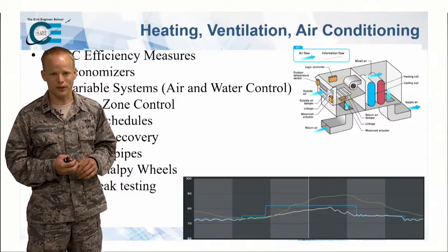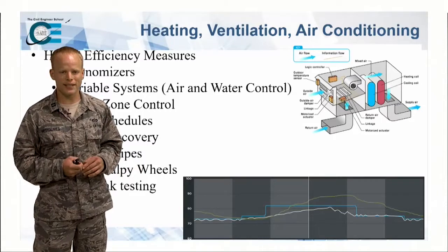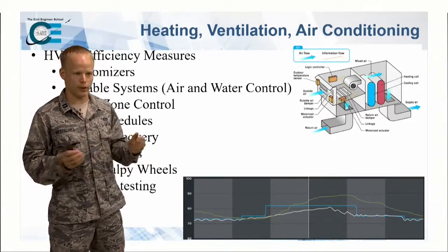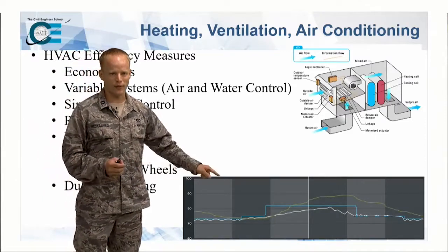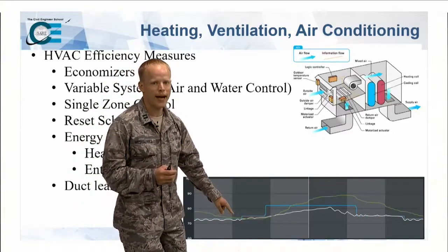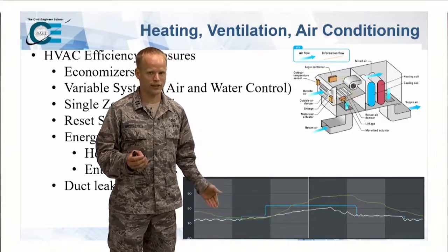Now, reset schedule. Most places we use this in the Air Force. This is actually a picture from my Ecobee, because I am a geek like this at home. I love putting all this home automation stuff. And so this is our Ecobee. This is a reverse reset schedule. So if we look over here, we have during the night, I like it cold, so I decrease the temperature.